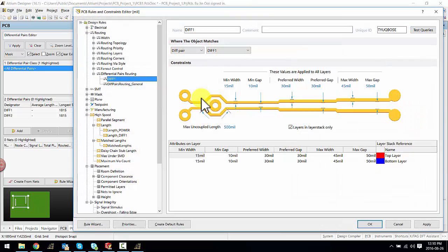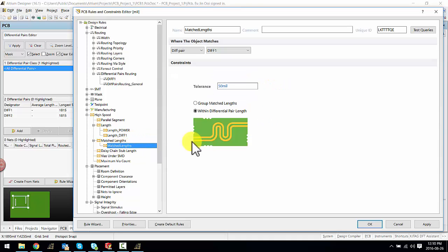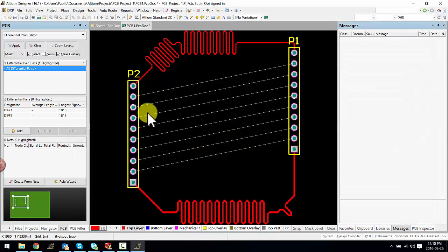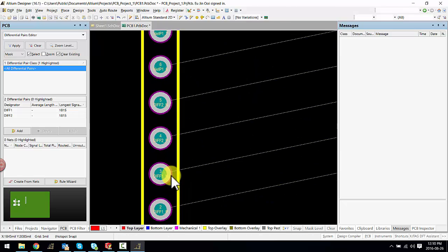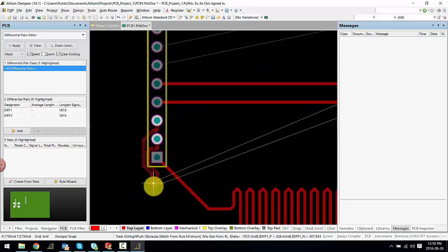A differential signaling system is one where a signal is transmitted down a pair of tightly coupled carriers, one of these carrying the signal, the other carrying an equal but opposite image of the signal. Differential pair routing is a design technique employed to create a balanced transmission system able to carry differential signals across